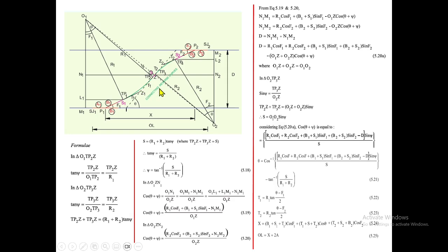So we have to make some compromise, and use many ways and means to find out our required parameters, particularly the deflection angle. First we want to know the tangent lengths of this one and this one. We need to know the deflection angles, and further the angles at the centers. As usual, because of the straight, there is an involvement of one psi angle, which connects O1 and O2. So let's proceed. First, we will take this side.